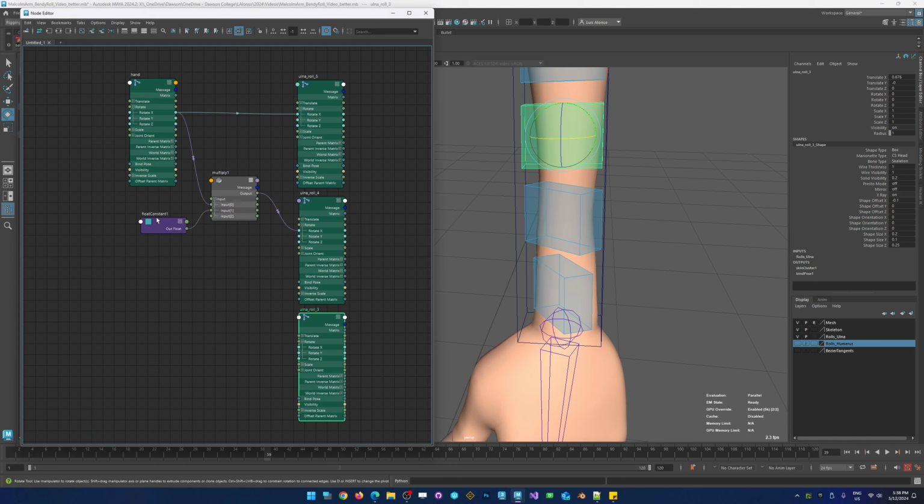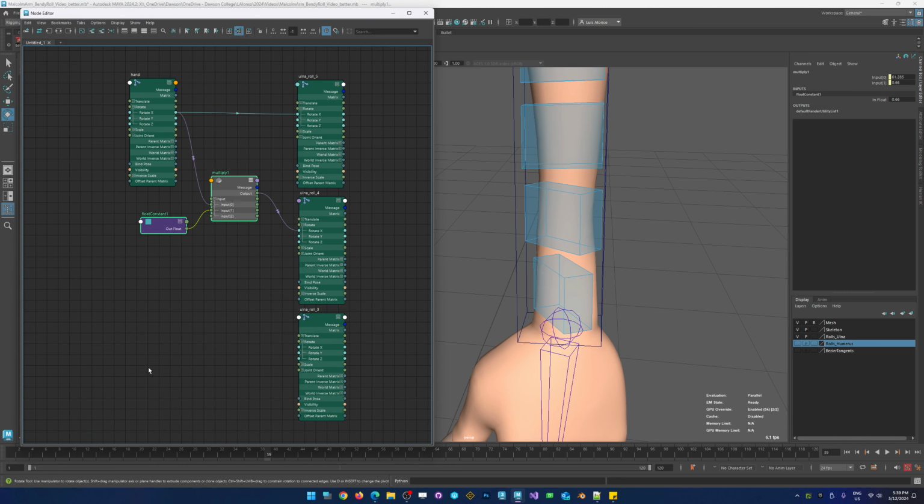Now, this is something you need to get used to. For those of you that haven't felt the pain, to be able to copy paste this, you cannot press Control-C, Control-V. You have to press Control-D for duplicate. And that takes a little time until your brain gets used to that. So I just thought I'd mention it because it can really mess up your scene, and then you have to find what it brought in and delete the stuff that got copied incorrectly.